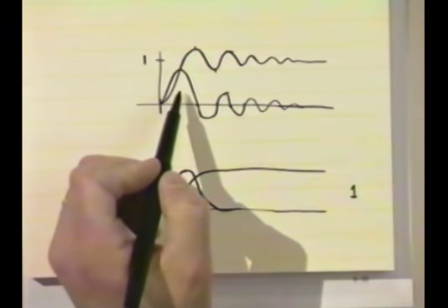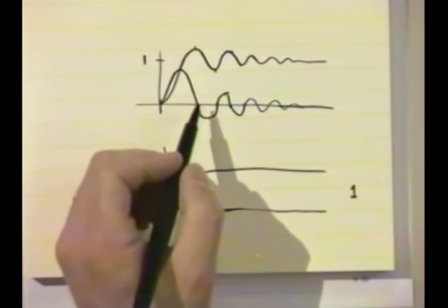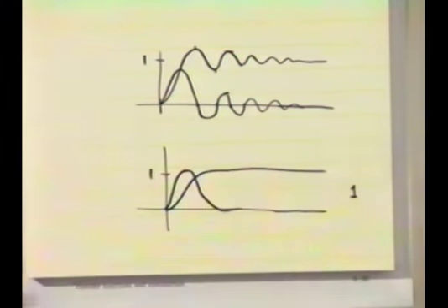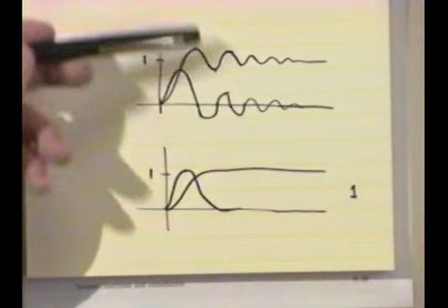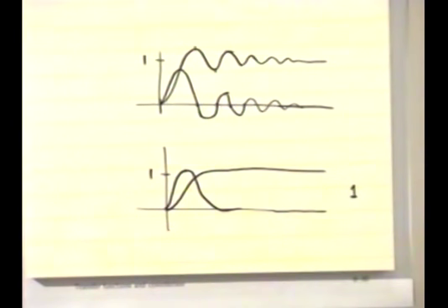Because what's going to happen is you get a big contribution here, right? Then you have a big contribution here, but it's not subtracting now. It's being added. You take the absolute value of the area. So you take the sum of the areas of this, and you're going to get a number probably around 3 or 4. And what it says is that there's two bad things about the system. If this were a suspension system, there's two bad things about it. The first is that when you go over a curb, the whole thing's gonna vibrate for a while, which is not good. But what this says is there's some sequence of curbs you can go over where the response of the thing will actually be extremely large. It'll be 4 times larger than the size of the curb you've gone over.